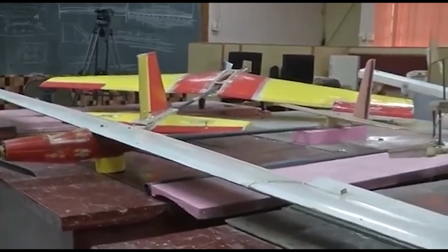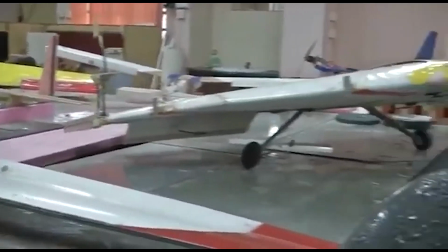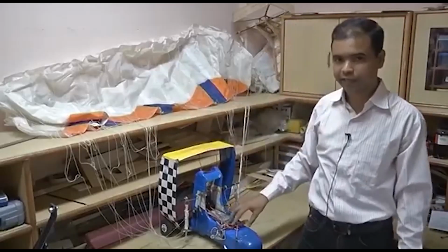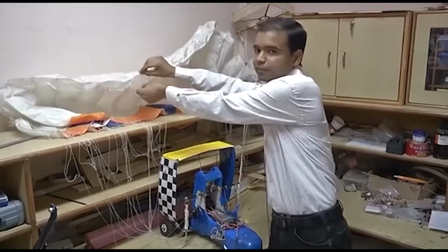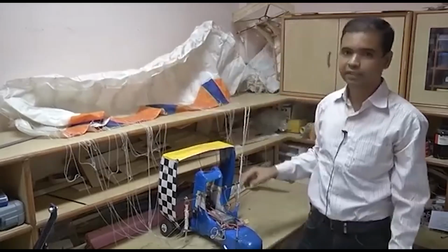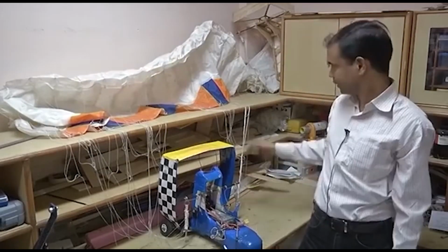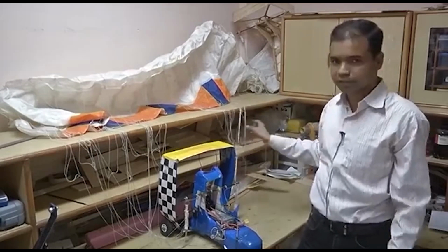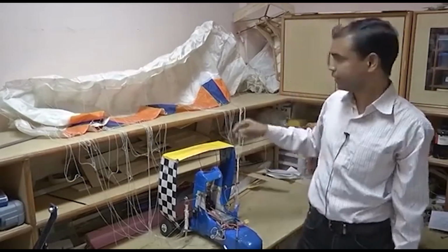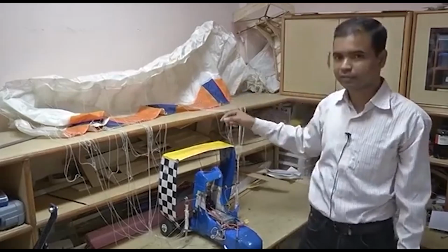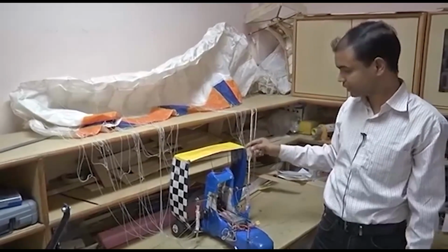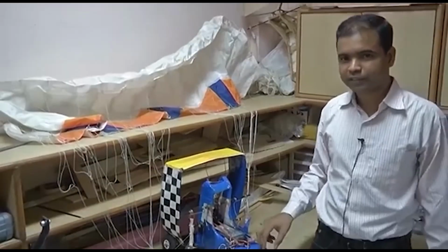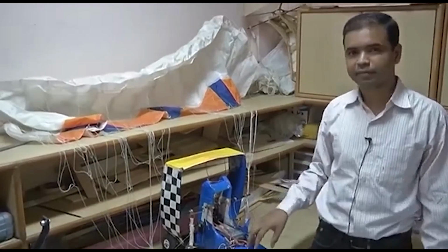A glider which has a very good gliding ratio, about 45. This is the powered parafoil. The parafoil is attached to the truck. Here are cells and they fill with air, and its cross section takes the shape of an airfoil, and this is attached to the suspensions. When the suspensions are pulled in a symmetrical manner, the camber changes and it works as an elevator, and at the same time if we increase our throttle, it climbs. For the steering, the suspensions are pulled in a differential manner.